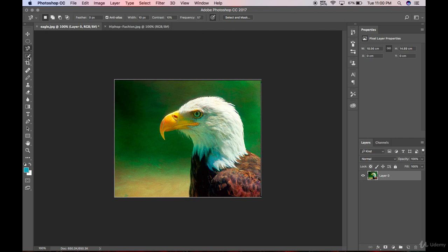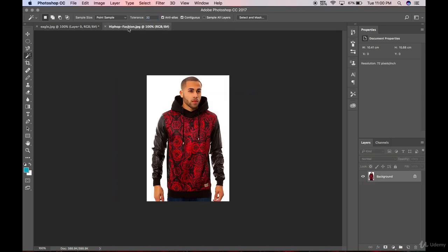The next tool in this option is the magic wand tool. What does the magic wand tool mean? It means that if we want to select a single color, it will select it automatically. When I press on the green color, it will select the green color. Why is it selecting only this minimum area? Because the tolerance is 32. We'll cover all this detail later. Let me just show you a quick demonstration of this tool.